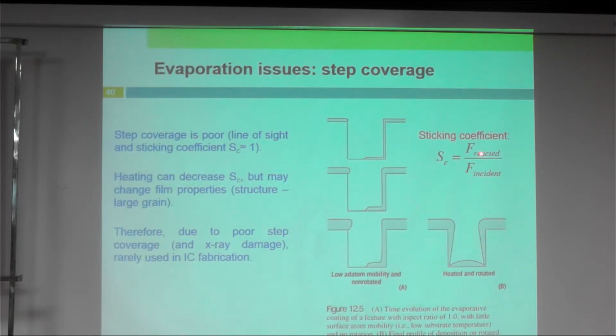At the same pathway, then this pathway is deposited here, but of course, the whole pathway of the evaporated material is just covered in this narrow section. So that is why you cannot have the same film thickness at the wall of this trench.